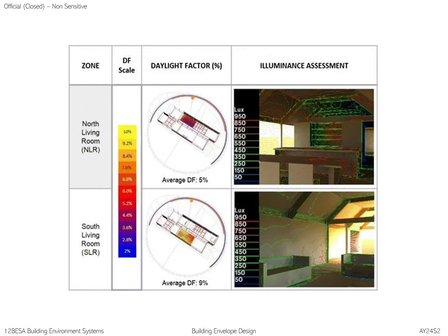For example, the red lines are between 850 lux onwards, whereas the green lines, if you trace it back, are 250 lux, 200 lux, which is sufficient. But some might prefer to go up to 300. So what do you do about it? And actually, 150 and 50 for functional space is not that sufficient, but maybe in a bedroom setting, I don't know. It's up to the designer to specify it. Okay, so these are important data to have.